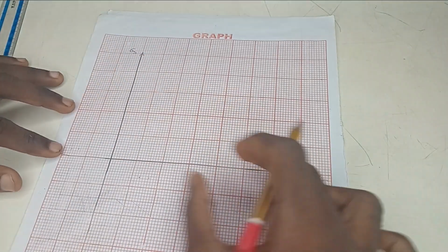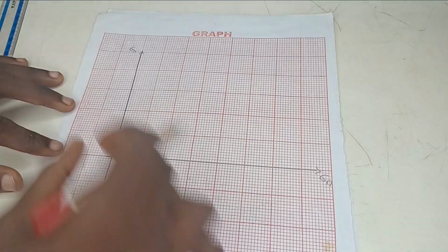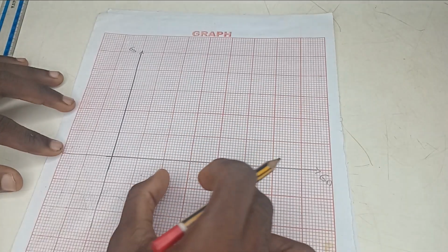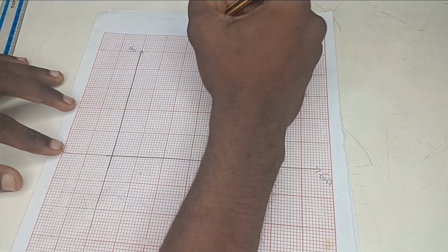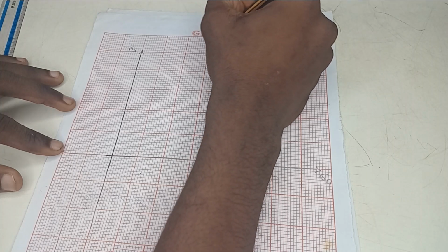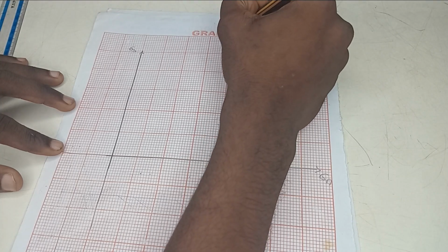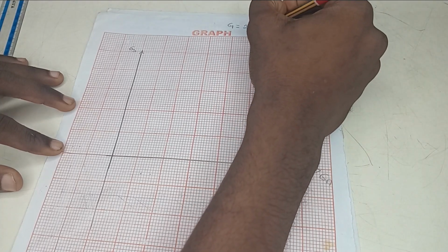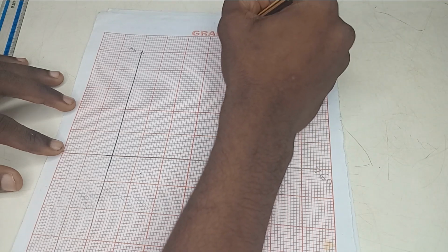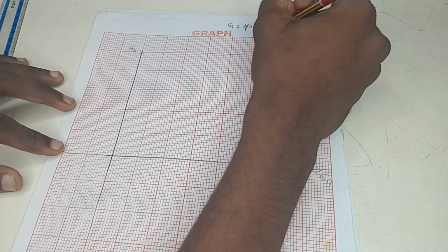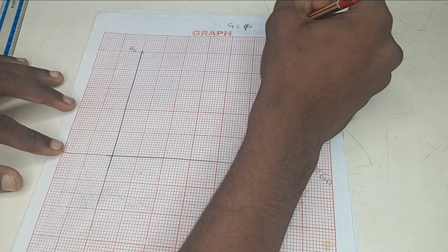Okay. So your next step is to what? You must choose the same scale for both the y-axis and the x-axis. The same scale. So we know that what is being given to us is, for the greatest principal stress, sigma 1, 40, and for the least, sigma 3, 20.